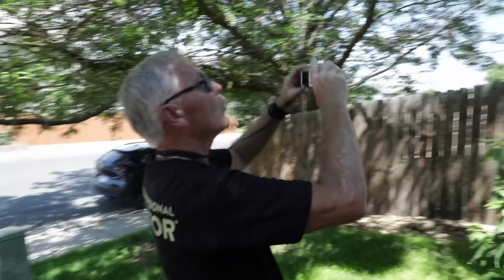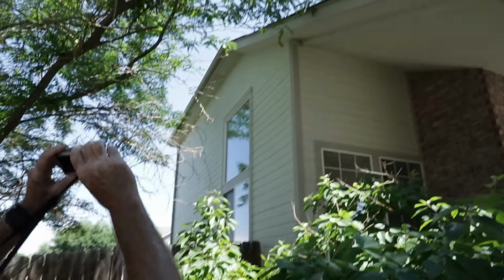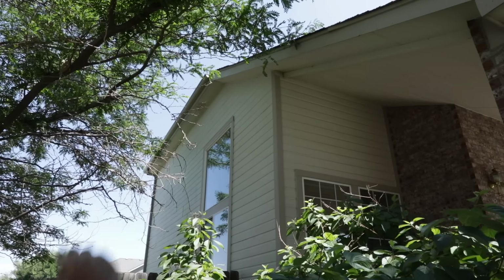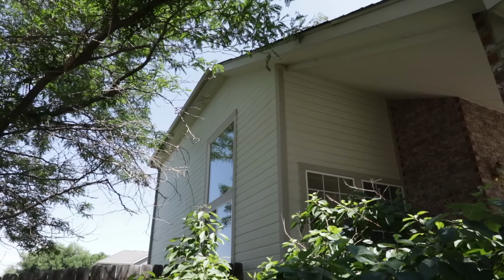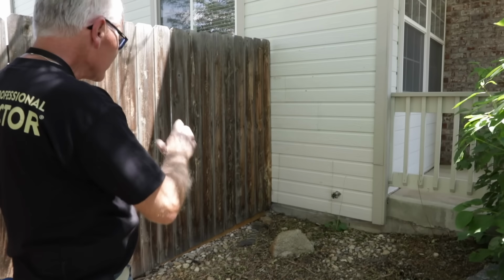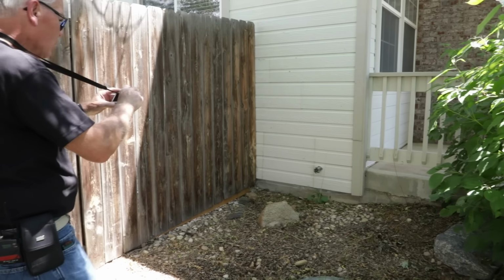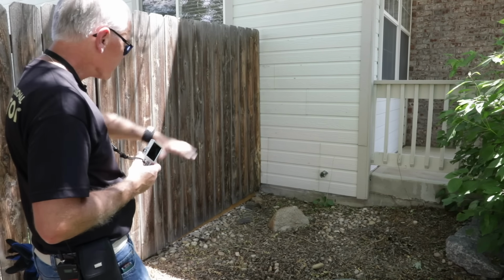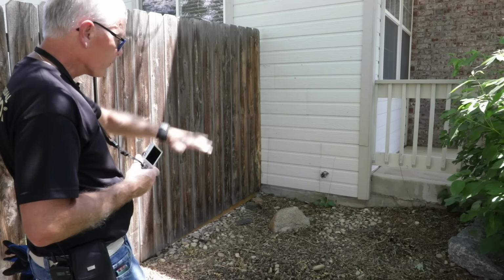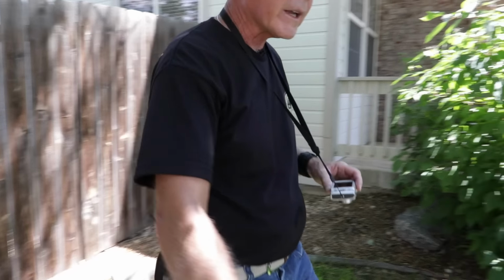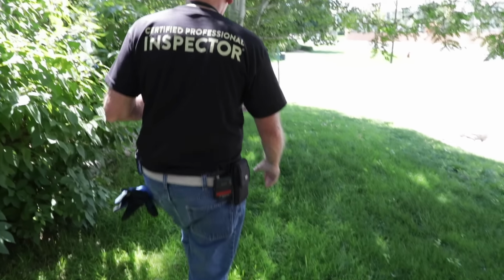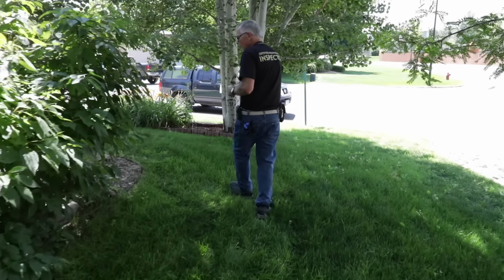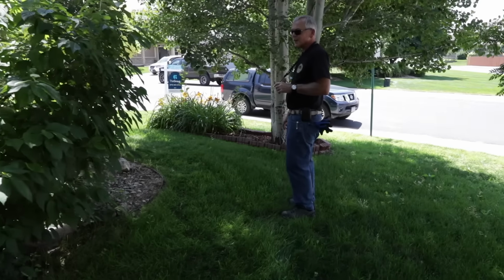We've got some tree overhang up above. It's touching the fascia and is hanging over the roof, so I recommend trimming that. Grading is not ideal here. It's a little low, so I'm going to recommend some additional fill and regrade so the water flows away from the house. I will also look at the grading out here in the front, and this all looks pretty good. We've got a good slope on it. That's what we're looking for.